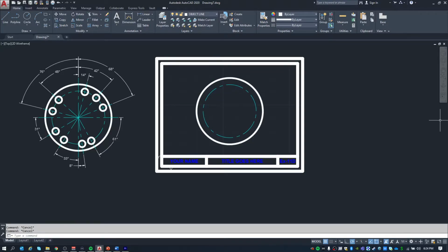Okay. So now we need to start drawing all of these circles. So you're going to have to do a little bit of addition and subtraction in your head with this, or with a calculator if you need to. But all the measurements that we're going to be typing into AutoCAD to make these different angles are going to be off of the x-axis.